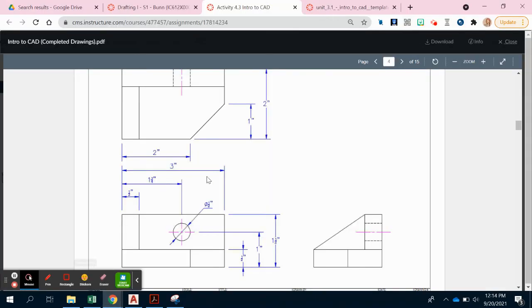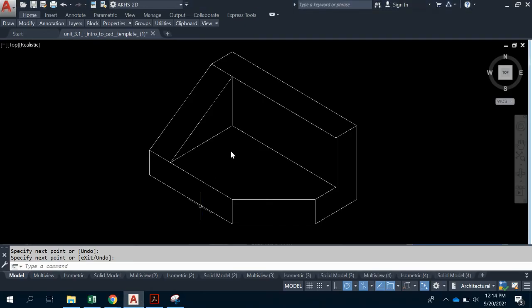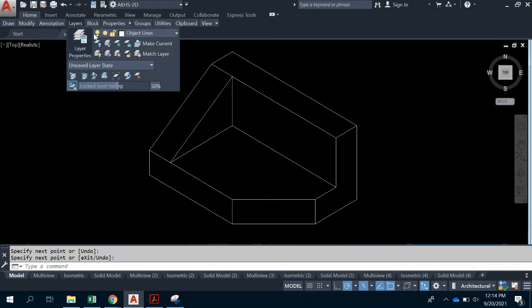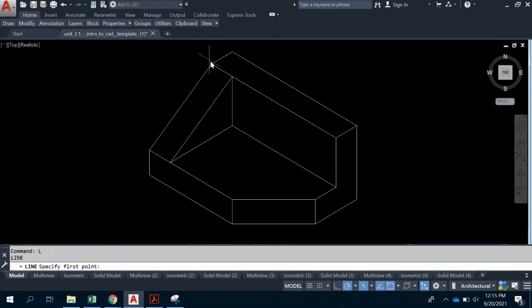We're going to check back at our dimensions and find its location. So it's 1.75 from here, and then we are 1 from here, or 0.5 from here. So I'm going to go 1.75 from here and then down 0.5. I'm going to switch to construction lines again, draw a line. So from here, we're going to go 1.75, enter, and then come down 0.5, enter. And then that is your center point for your ellipse.